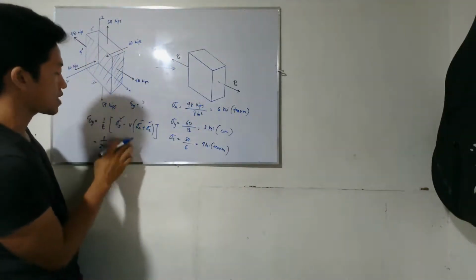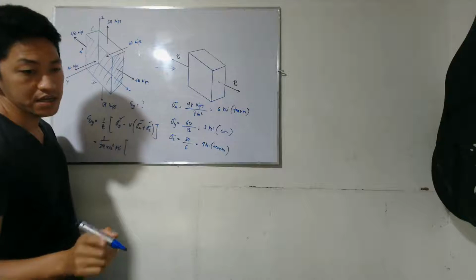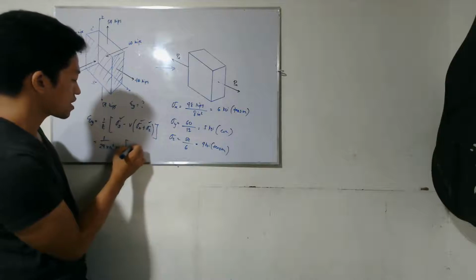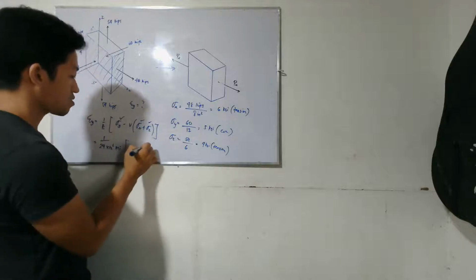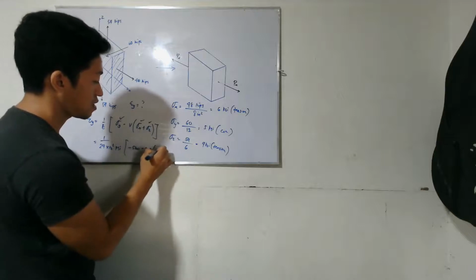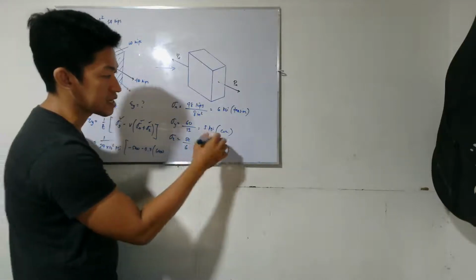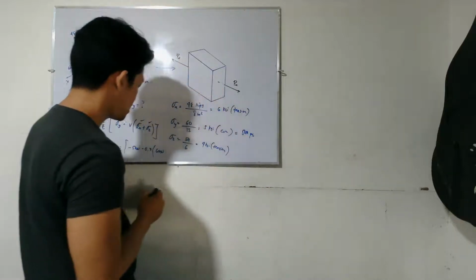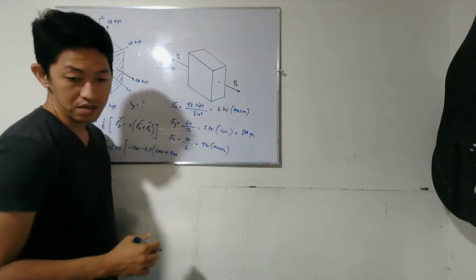Now, stress in the Y minus. In the Y, again, compression, we take that as negative. So negative 5,000 minus 0.3 times sigma X, 6,000. Again, this is in PSI. This is equal to 5,000 PSI, plus 9,000.